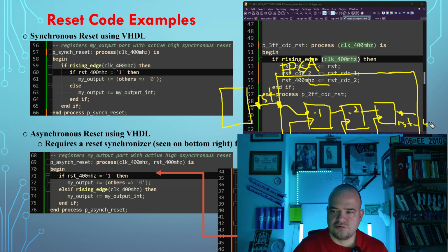So this one is just synchronizing with triple flip-flops, and at the end it could be metastable, of course, depending on your PVT values and your technology, values incoming from the FPGA you are using, plus this 400 megahertz. There are some nice calculation tools. Of course, you need to provide 3 parameters from your FPGA device datasheet.